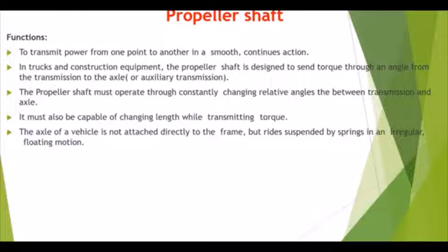It is also a hollow tube which extends from your transmission to your rear axle housing. At one end it is fastened to the axle housing by bolts, and at the other end it is fastened with the help of your torque ball. The drive shaft generally fits onto the torque tube, and a universal joint is also located in the torque ball. So the thrust produced will be transmitted through the torque tube to the torque ball, then to the transmission, and finally to the engine.